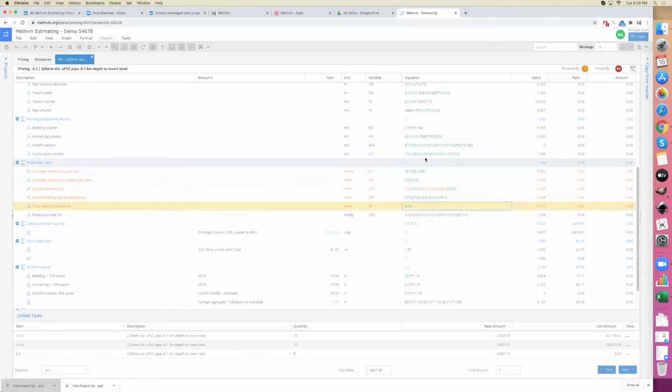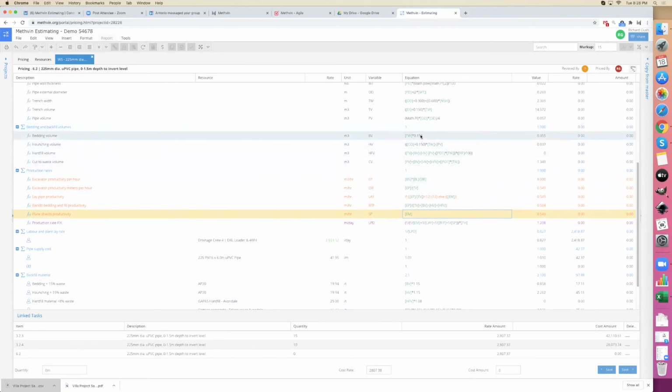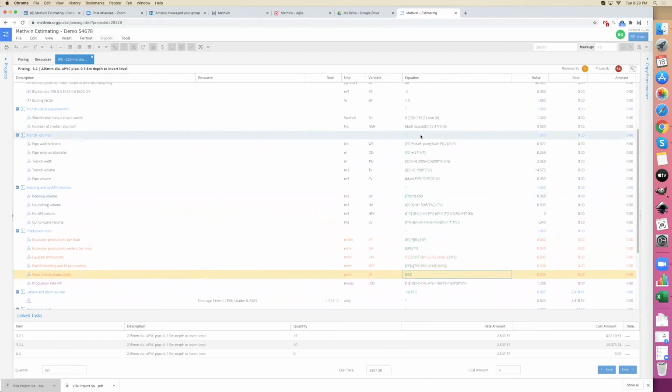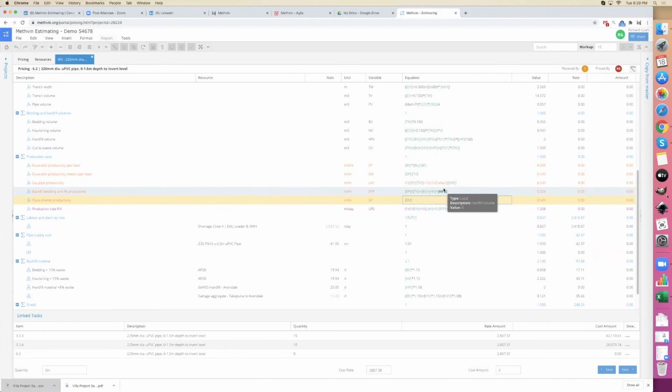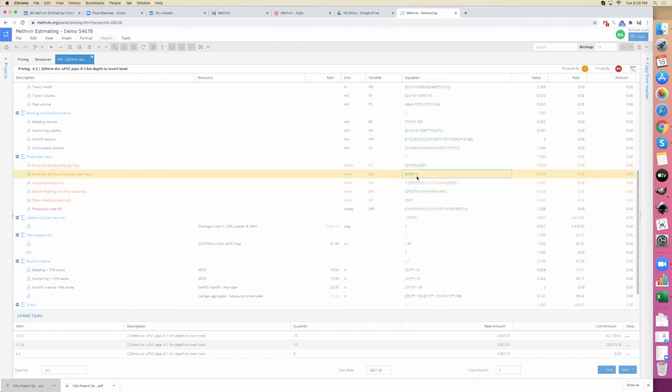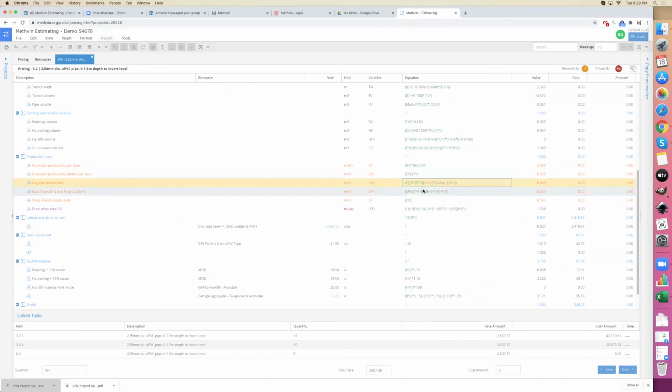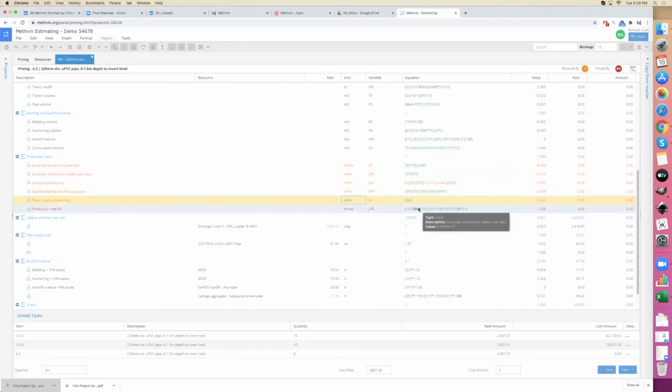I have determined this from the bucket size of the excavator we're using, the number of cycles that the excavator does, and then the loose volume of the bucket size. It gives us cubic meters per hour. You divide that by the trench volume, which gives you the meters per hour that you're doing. And then I've used all of those equations to determine, from the excavator and lay rates that I know from experience, the lay rates, the backfill rates, and all the rest. And then I've used the resistance formula, same as electricity, for those 4 line items. So it's 1 over the excavation rate plus 1 over the lay rate and so on, divided all over 1. And that gives you a production rate of 1.2 at 6 meters.